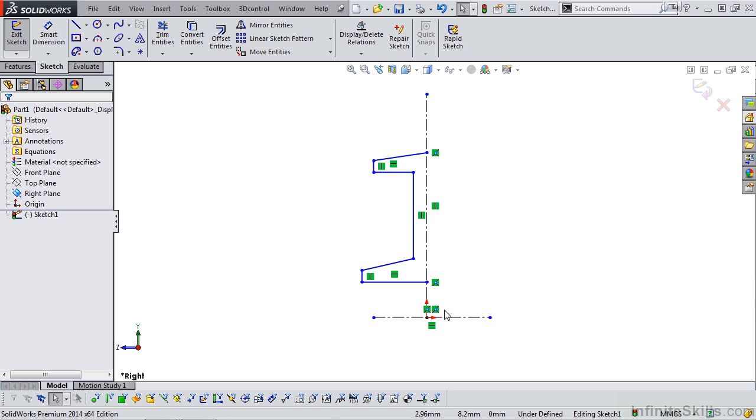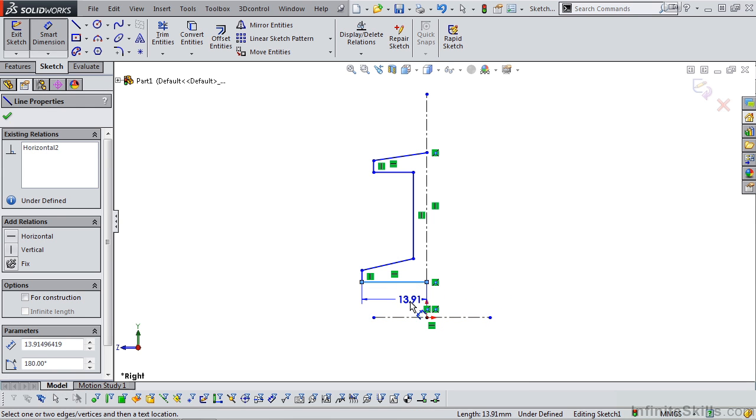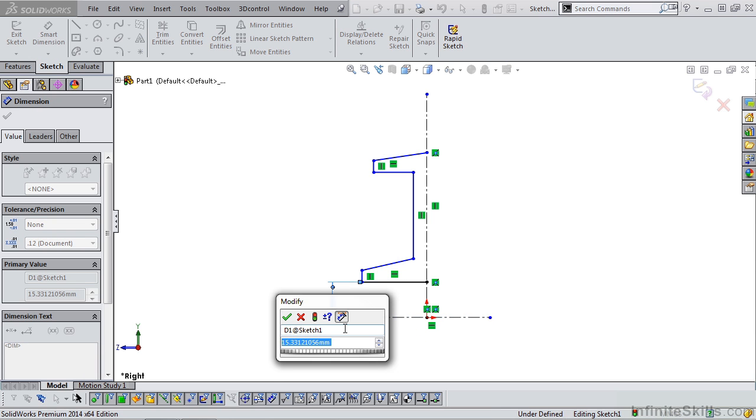Let's zoom out a bit. I'm going to tap the S key, go to my dimensions. Now I'm going to start with this first dimension here. This is diameter 30. Now notice I selected the line, next the center line, and this is the radius, which would be 15. I always like to create my sketches using the same dimensions as shown on the data I'm working from. Since that was provided as a diameter 30, if I move my cursor below the center line, it switches over to a diameter dimension.